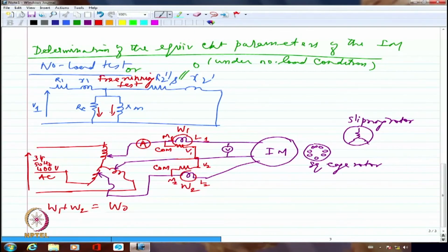If I just reverse, 180 degree out of phase will automatically make one of the angles, whatever we have, 30 plus 5 or 30 minus 5, come out to be maybe 180 minus something like that, because of which you will automatically see that the reading becomes positive. So you would not have this difficulty if we are talking about reversing the current coil.